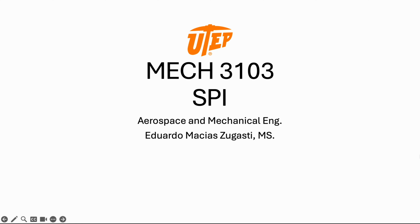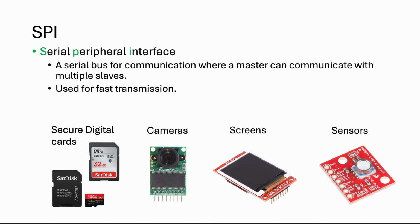Today we're covering SPI. SPI stands for Serial Peripheral Interface. It's a serial bus communication where a master can communicate with multiple slaves, though not exactly at the same time. It needs to select one slave to communicate with, and then it can select another slave to communicate with.